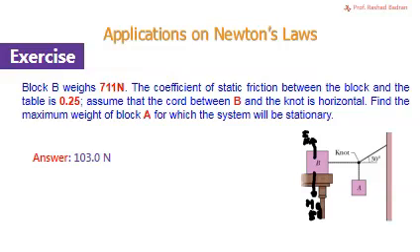Along the x-axis there is a tension in the rope, because this weight will put tension on the other two ropes, and this one has a tension in this direction, call it T1 if you like, and there is a static force of friction, where it is supposed to be on the verge of slipping, Fs maximum here.